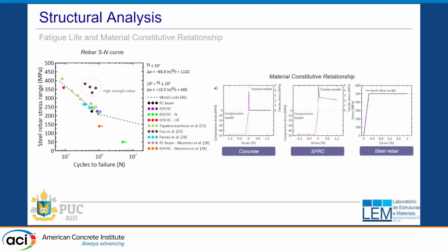So that would allow us to start with the steel rebar stress range, the stresses that the steel rebar experiences. Note that there is no fatigue curve for the steel rebar if you're in the elastic range, as long as you're in the 10% or 20% in the serviceability level.